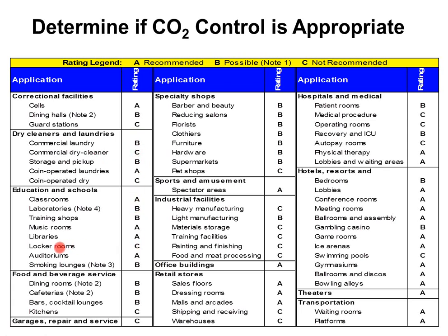Locker rooms, they already stink absolutely horrifically. Hockey gear shoved in there for 3 months. You do not want to cut the ventilation air back in a locker room. It'll smell even worse. Kitchens are definitely an issue. You can do DCV in kitchens for the exhaust systems. You just don't use CO2 sensors for it. There are DCV systems specifically for kitchen hoods and stoves, and typically it's some kind of infrared/thermal sensor that they use in those cases.